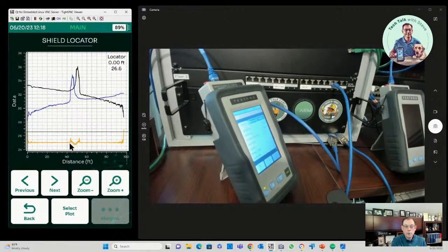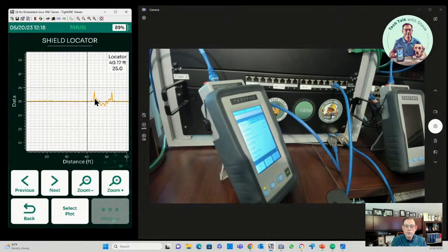We can see here on this pulse TDR trace at the bottom, and if we move this cursor in, we can zoom in on this. If we get right out here, we are getting close to that halfway point. We're looking at about 43 feet, and then we continue on, and this goes all the way out to right about 52 feet. So we've got a section of cable, probably about 7 feet in length, where we've got an issue with that shield.